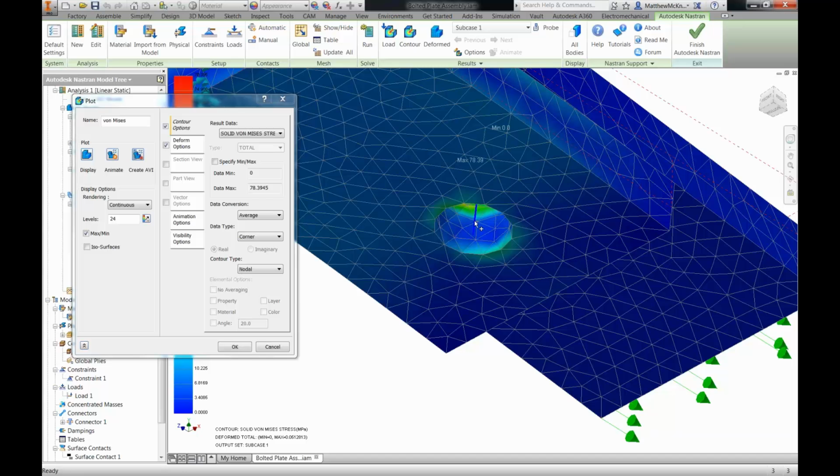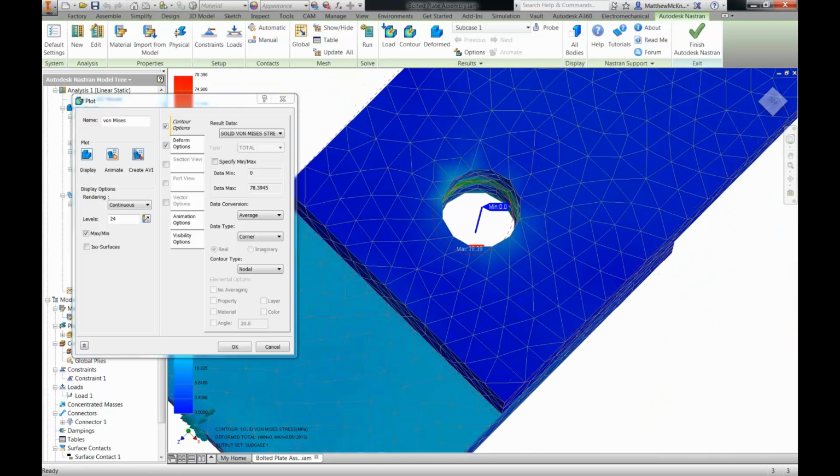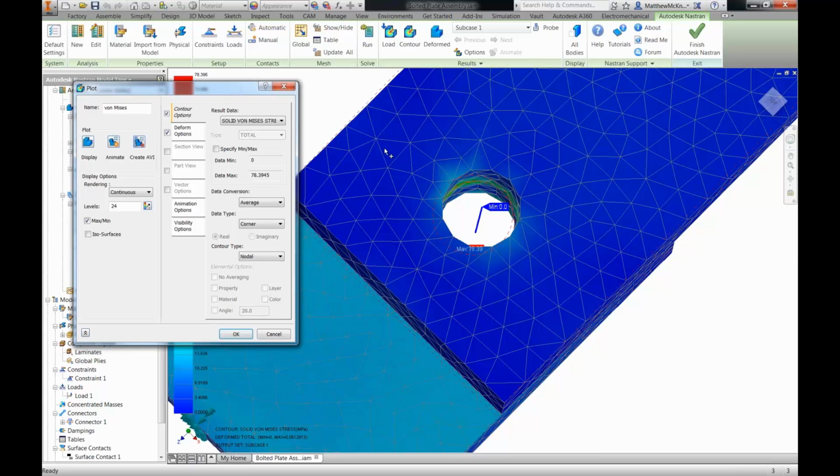There's effectively a beam element, and you can see it right up through the center of our part there, and from that beam element there's actually rod elements that extend out like a wagon wheel to the elements and nodes of the surrounding edge that we've chosen. In real life, the washer would extend beyond the perimeter of the edge of the hole and would be placing a tensile force down on the face, as well as potentially a torsional load as a result of the torque load that's applied to the part, which is a very complex joint to try and understand.